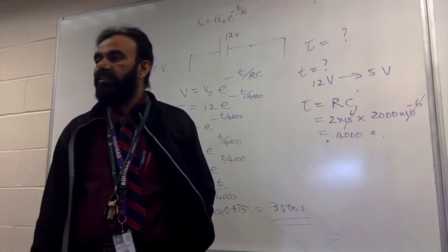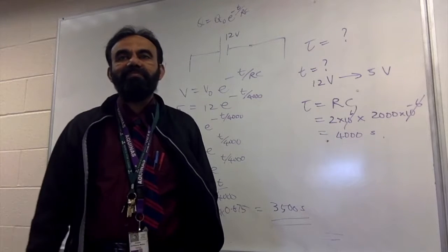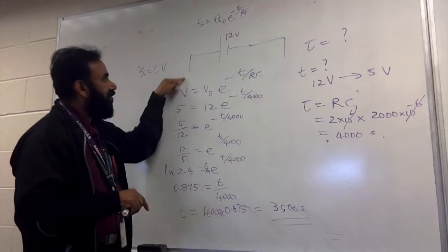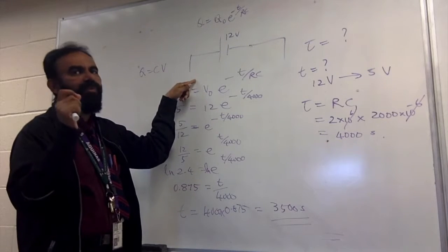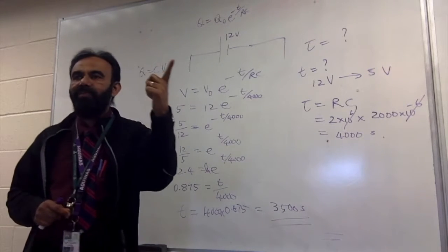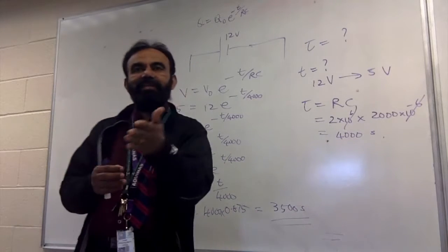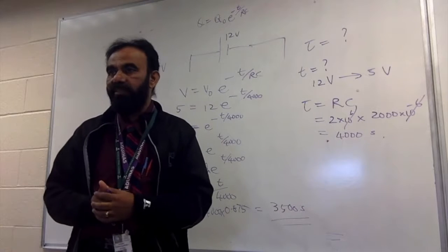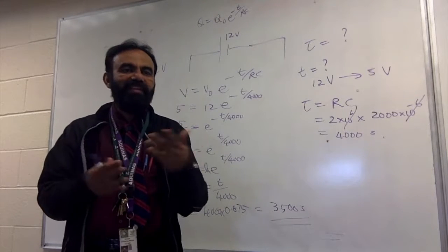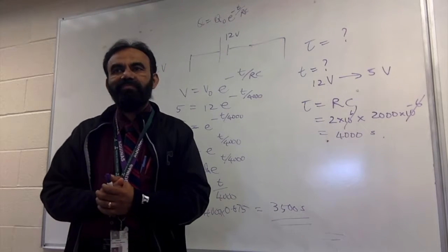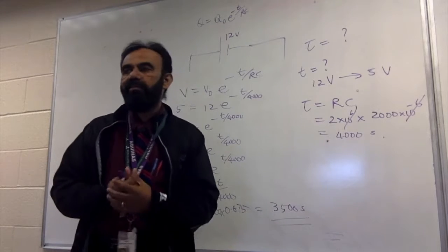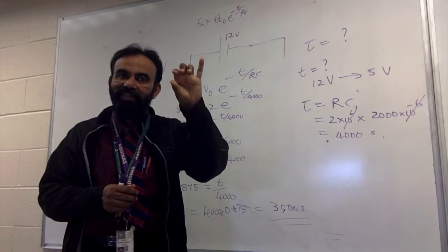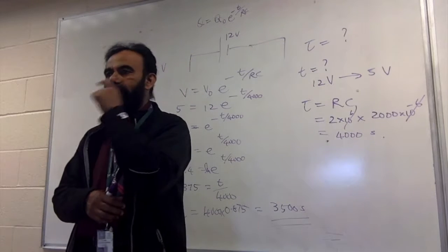a capacitor basically. So when I put a capacitor in the circuit, if anyone touches the switch once, even one pulse, the capacitor charges fully, and then I can set up a delay according to the choice of resistance and capacitance, right? And I chose a delay of roughly 10 seconds. Almost, the time constant was 10 seconds. So the relay was held for that much time and then goes off.